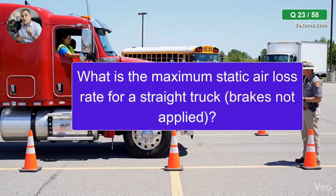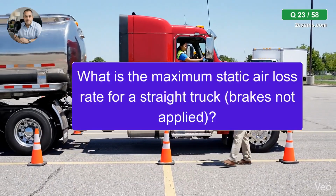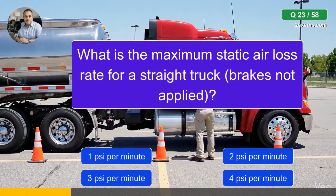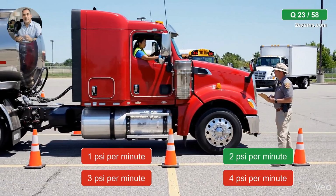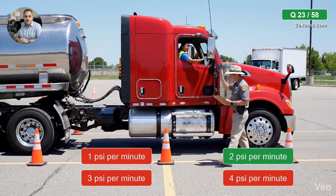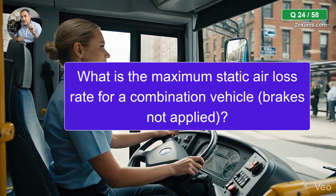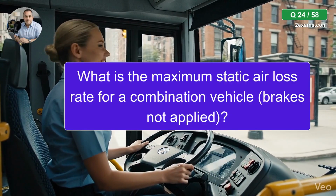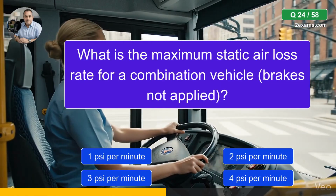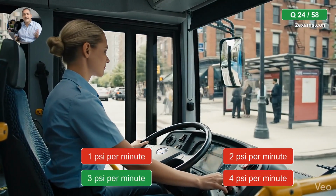What is the maximum static air loss rate for a straight truck, brakes not applied? The correct answer is 2 psi per minute. What is the maximum static air loss rate for a combination vehicle, brakes not applied? The correct answer is 3 psi per minute.